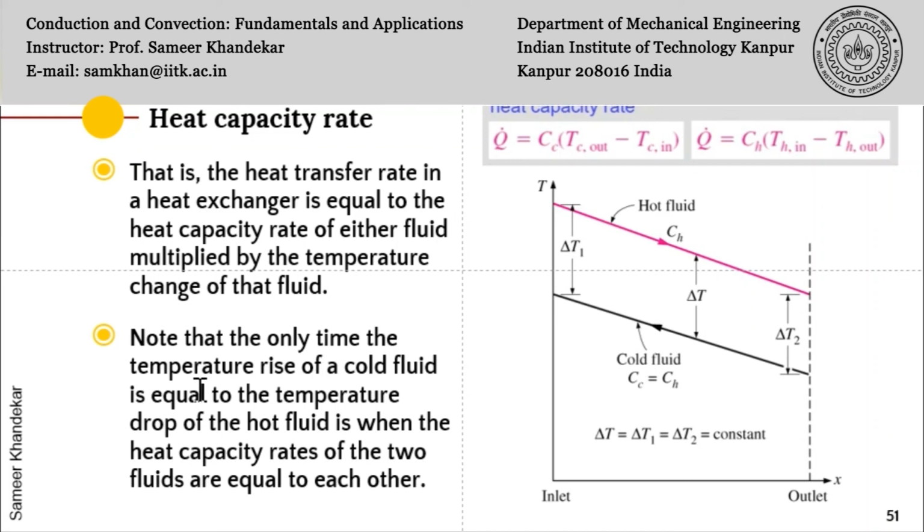The only time the temperature rise of a cold fluid is equal to the temperature drop of the hot fluid is when the heat capacity rates of the two fluids are equal to each other. Otherwise, in all other conditions, and this is true for any type of heat exchanger for that matter,